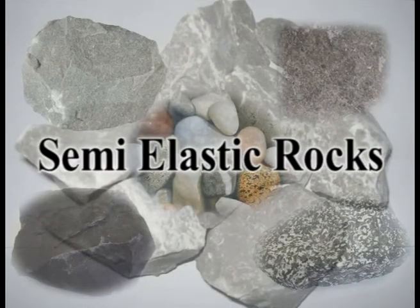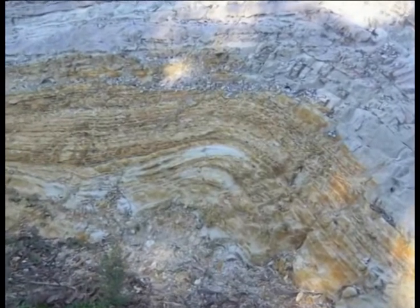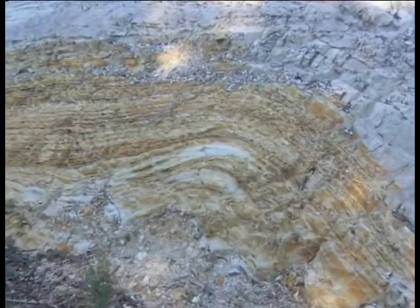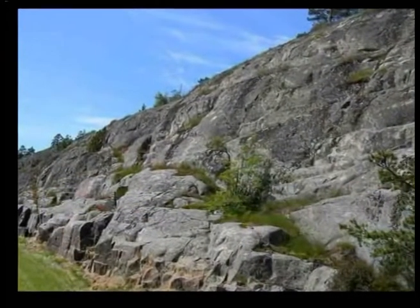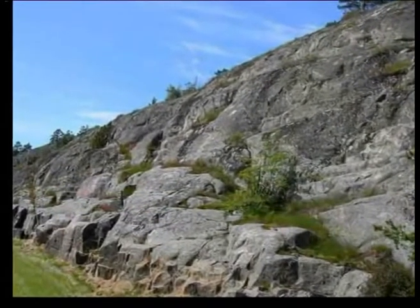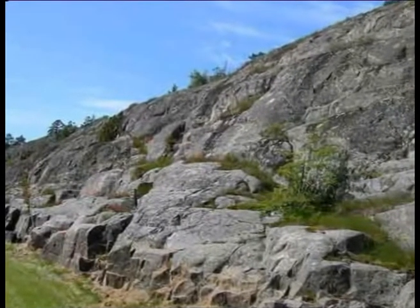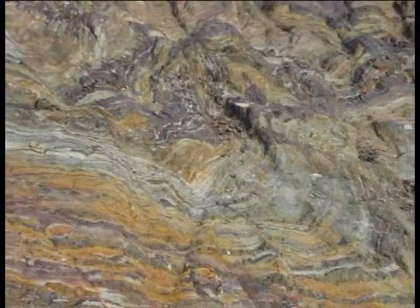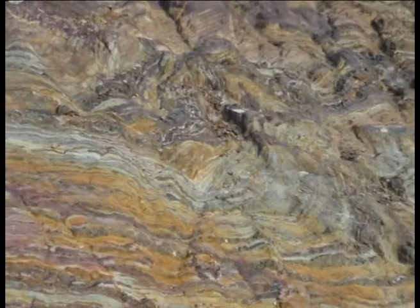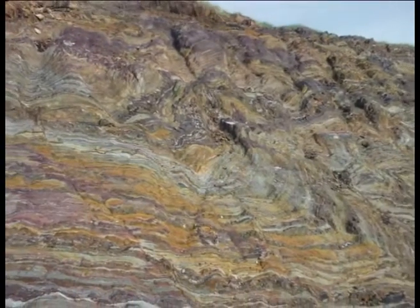Semi-elastic rocks. Semi-elastic rocks are coarse grained, slightly open packed with some porosity and very minor structural discontinuities. Coarse grained igneous rocks like granites, and some massive compact sediments like sandstones and dolomites, may often show semi-elastic properties. In this group, the curve indicating the modulus of elasticity has such a characteristic that its slope tends to decrease with